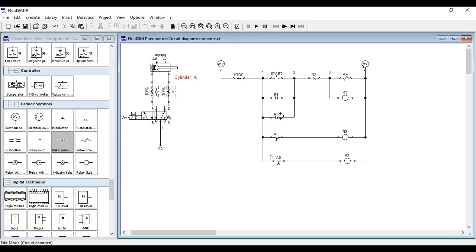However, the problem is that during the startup, R3 here is closed, or active, or energized, thereby making this closed, allowing the system to start by itself automatically. So we need some revision in the circuit. So the concept of AO, we'll just remove AO first and R3.